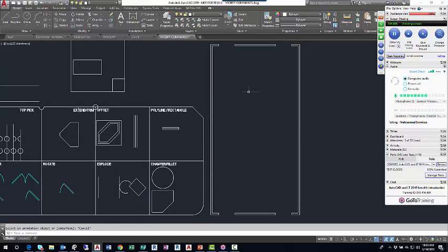In our drawing exercise, we'll have two windows, one at the top of the right side of the floor plan, one at the bottom. So I'll go offset, 1'6" is my distance, enter. I'll left click that topmost horizontal line, move down the screen, left click. I'll use the same value on the bottom, left click, go up and left click.